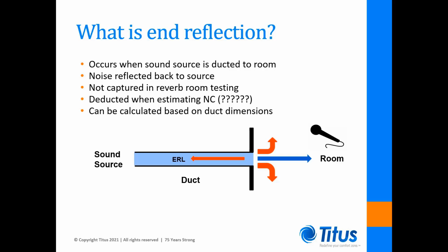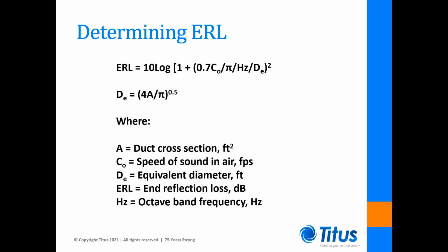Well, didn't this addition of ERL require manufacturers to retest their units? No, the ERL change didn't require manufacturers to retest anything. The ERL to be added was to be calculated based on AHRI research that developed the method of determining ERL based on discharge duct dimensions.